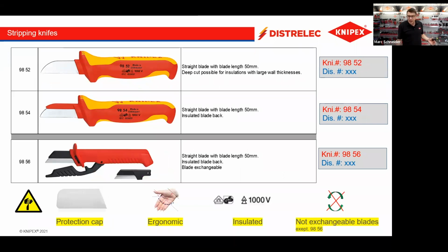So here we have three other types of stripping knives. The best-selling knife at Knipex is this one here, the 9852 with the straight blade. All these stripping knives that I showed you have a protection cap. They are very ergonomic and they are insulated for 1000 volts. They do not have exchangeable blades, with the exception of this one here, the 9856. With this tool, you can change the blades. It's also 1000 volt insulated.